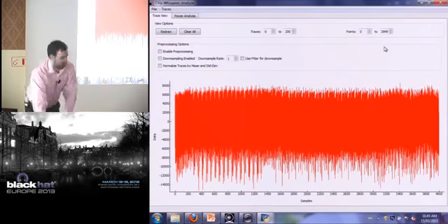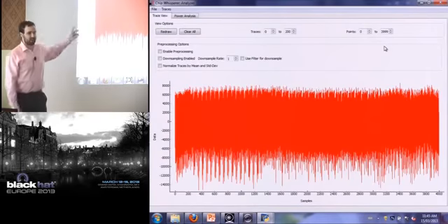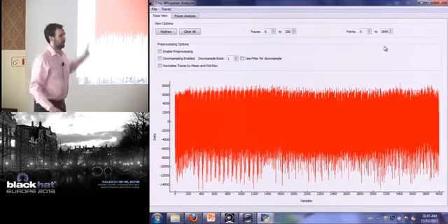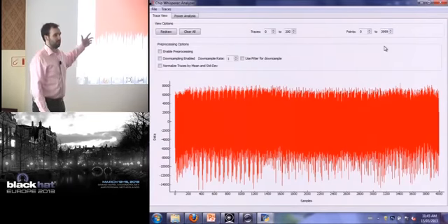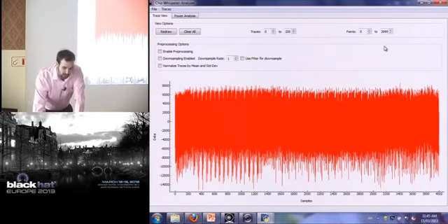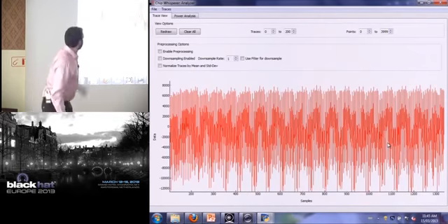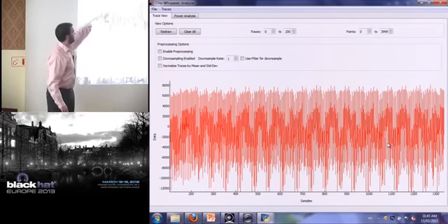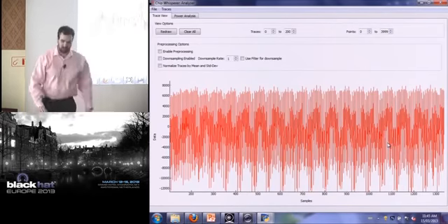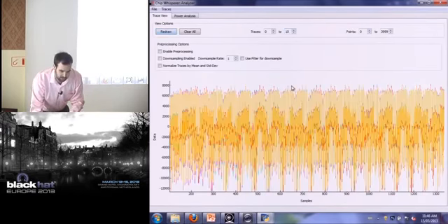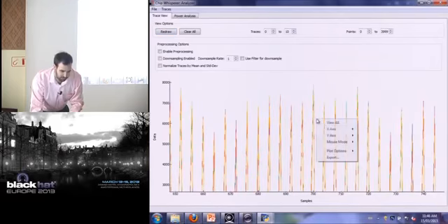And we can look at these power traces from a software AES implementation. It's a real AES library, and I didn't write this. This is used by people in actual products. So we can zoom in, for example, on part of the computations, and you can see some patterns in it. And you can plot, for example, a few power traces to overlay them, and you can start to see areas where they may differ a bit.